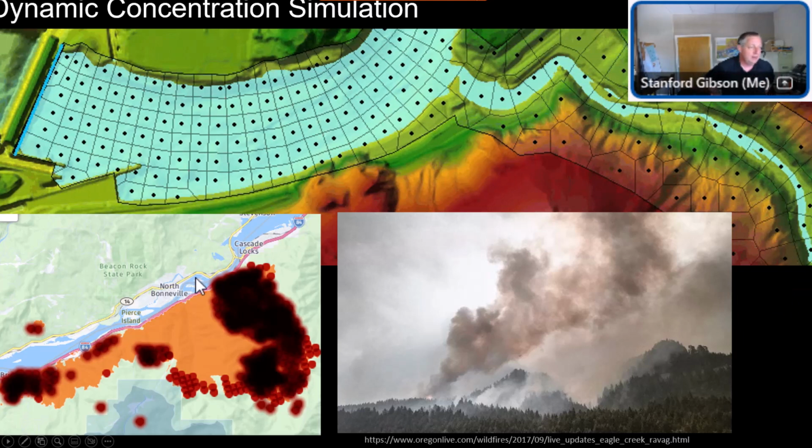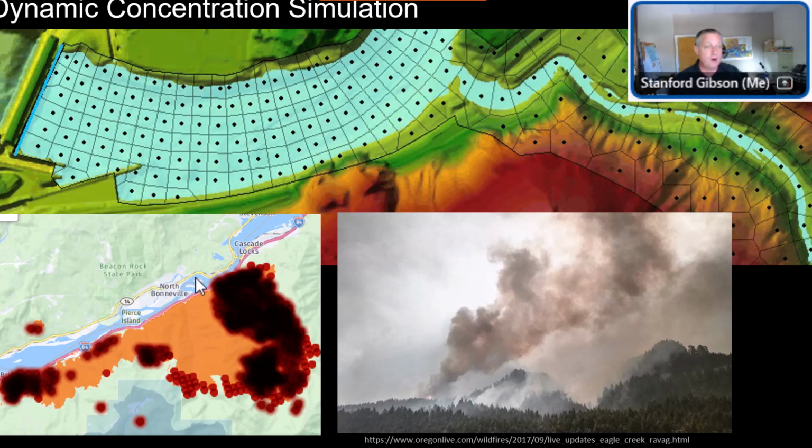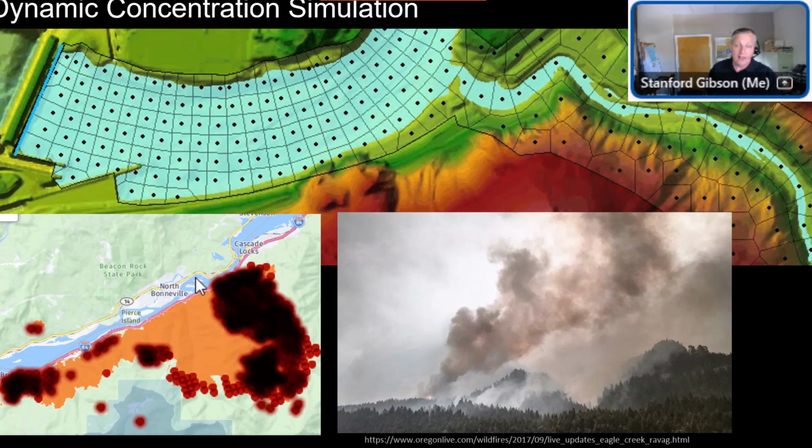And so this is actually an animation. It's a GIF actually, or a GIF, depending on who you are. I am agnostic about that. And you can see that now we can bring the sediment pulse into the Columbia River and see how it affects and if it reaches, which it doesn't, Bonneville Dam. So by providing these fixed bed sediment transport models, we allow these lower fidelity but still powerful sediment transport analyses on some of these rapid evaluation problems.